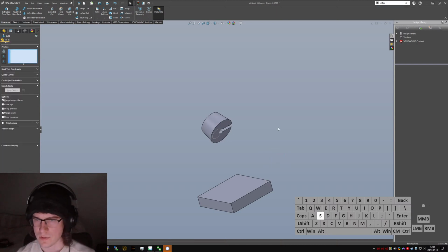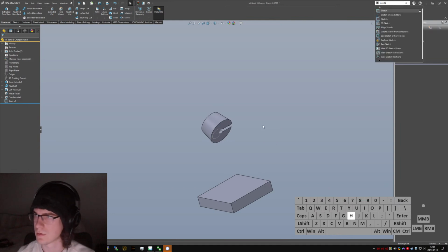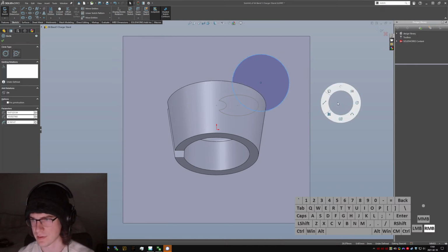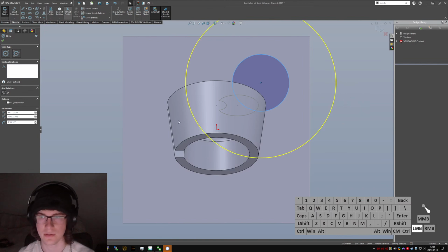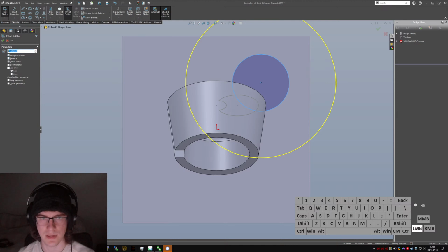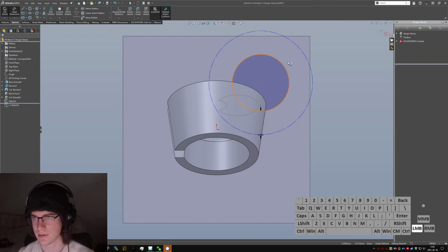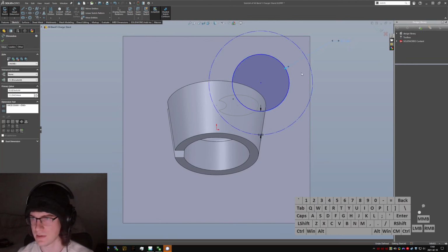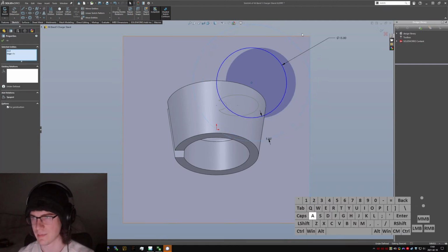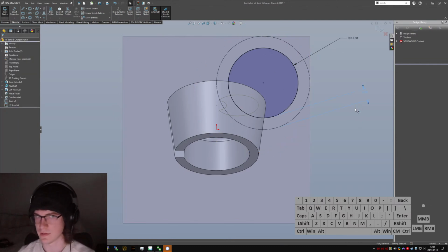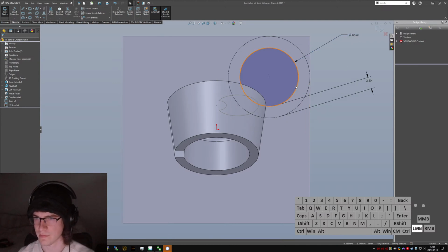Lofted. Nope, I need one more sketch. Do I have a convenient offset face? I do not. Let's add maybe 5 mm so I have plenty of clearance. That'll just be construction geometry. Decide how big I want the base. Say 15. That might actually be a bit big. The clearance might be a bit big too. What if it's only 2.5? 12.5? That looks good.